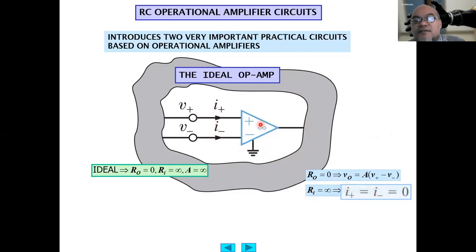No current enters the op-amp because of the infinite input impedance. Please remember this principle of the ideal op-amp.